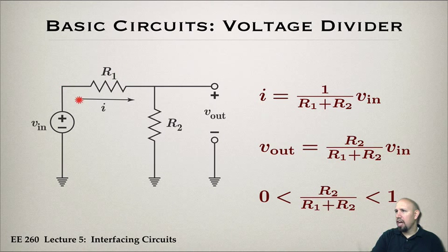This combines a bunch of stuff, and now when we hook up a load resistor, then we get a voltage division happening. Okay, and so that's important to keep in mind. So what we notice here is we have this ratio that comes out in the voltage division equation. If we have a large load resistance, which is what we had looked at before, then basically this is like the number 1, and we basically have that V out is equal to V in.